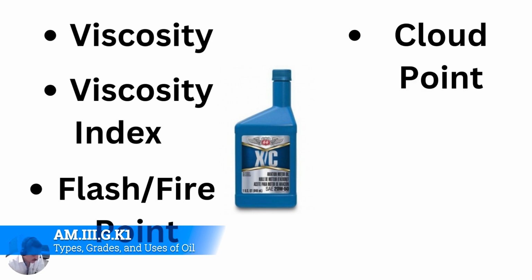Okay, so the cloud point. The cloud point of oil is the temperature at which its wax content, normally held in solution, begins to solidify and separate into tiny crystals, causing the oil to appear cloudy or hazy. We've probably all seen oil like this. If you've seen oil that's sat for a long period of time, you'll start to see that happen. But there's an actual temperature where that will induce this effect, and you don't want that, because whenever they refine oil and add additives to it to do different things, there's a reason they're putting that stuff in there, and it's for performance.